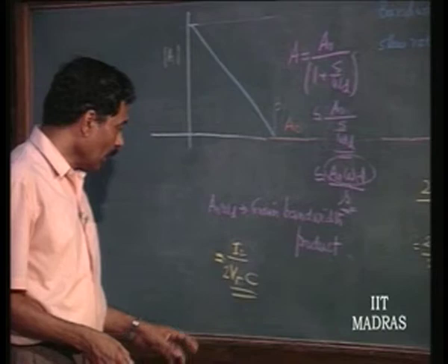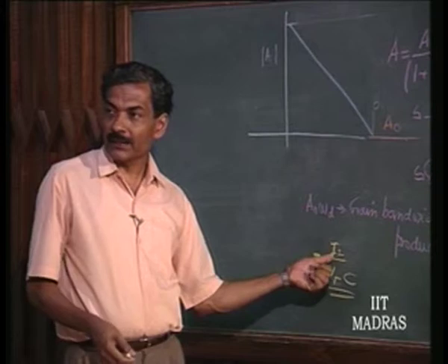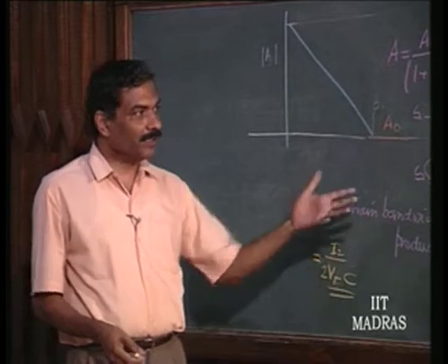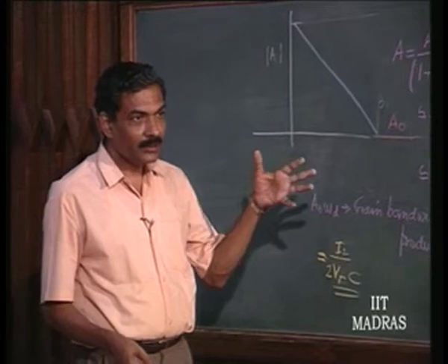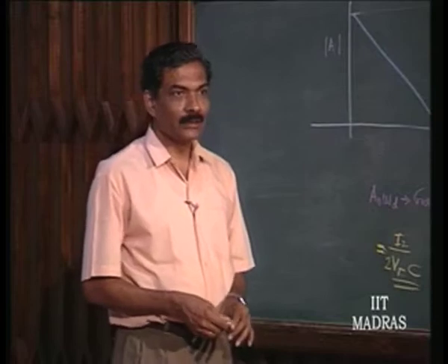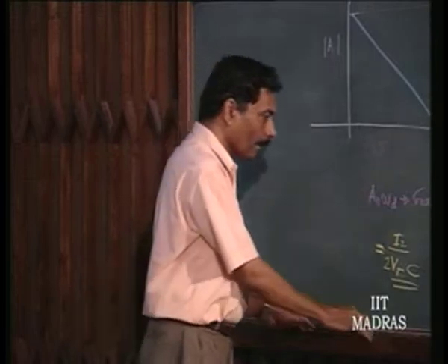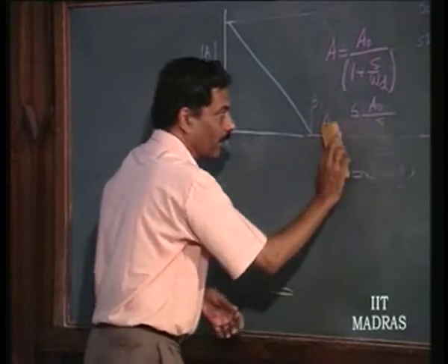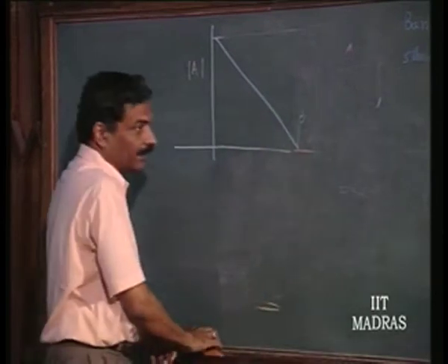Now, you know how you can manipulate the gain bandwidth product based on bias current and compensating capacitor. So, given the configuration, you immediately can now tell about the gain bandwidth product of the op amp. You should be able to, right. Is this clear? Now, this is a small signal parameter. Exactly in a similar manner, we can argue something for the large signal parameter. Please follow me very carefully here.